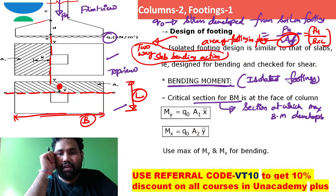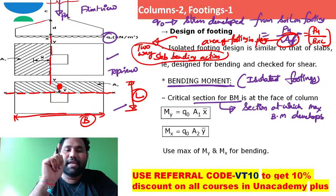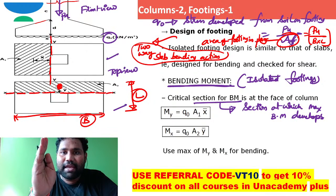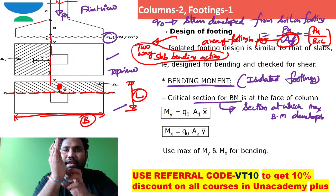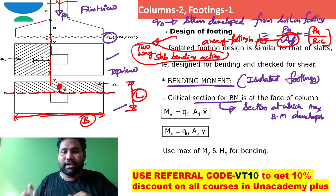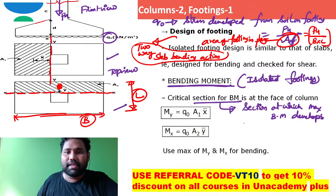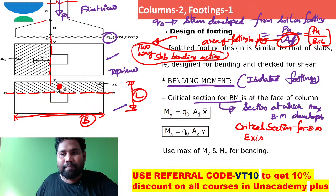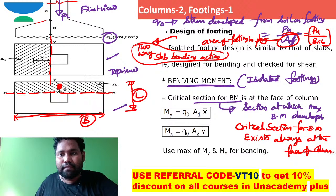I just want to convey one thing. The critical section for bending moment is always at the face of the column, in case of this isolated footing.